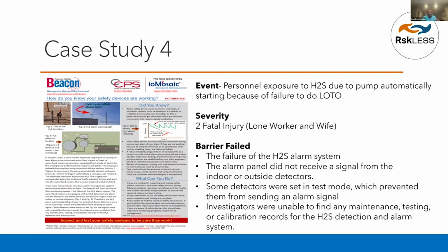What failed that day was that the H2S alarm was disabled. It didn't ring to the operator when there was a release of H2S as a result of the pump automatically starting, which was caused by the maintenance guy himself because he didn't do lockout tagout. And the painful thing was that when all the barriers that were called safety critical failed, the wife didn't see the operator, the maintenance guy, and the wife went to the plant to look for him. And when the wife got there, she also died because she was exposed to H2S.